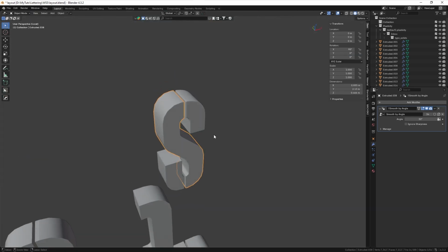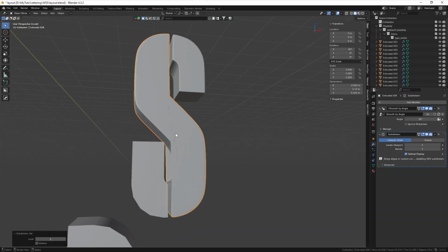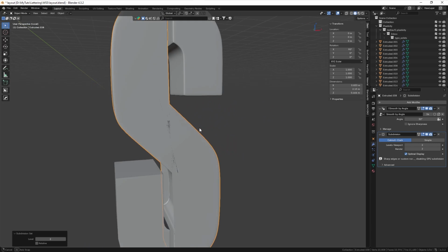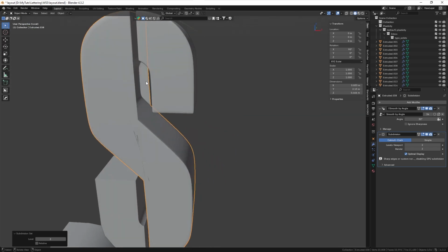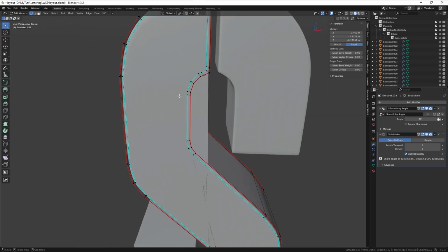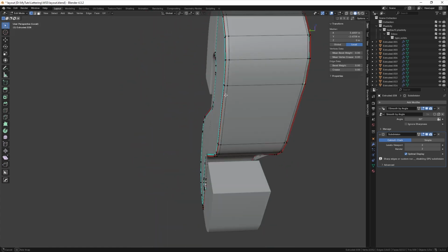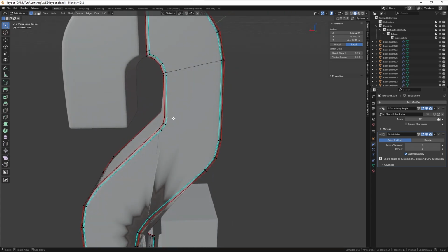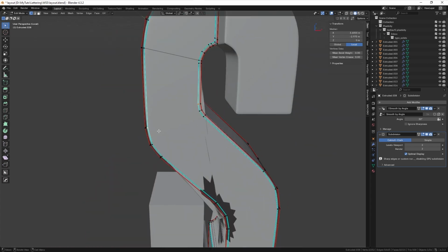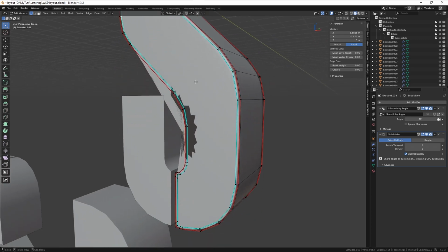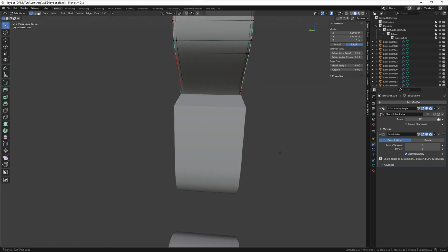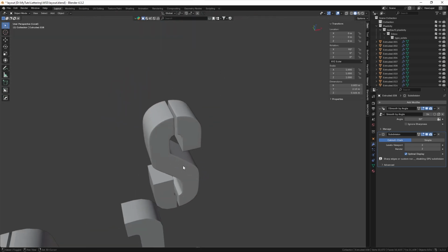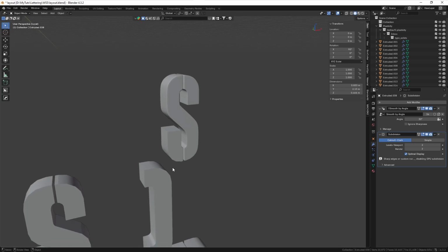Again, let's run the SubDiv. And here you can see that some weird stuff is going on. I mean, here that looks okay, but we can fix it simply by creating connections here. So select both vertices and press J for join. Do the same on the other side. And here on the bottom also. Now it's fixed, and we will do the same here. And we can continue tightening stuff up.